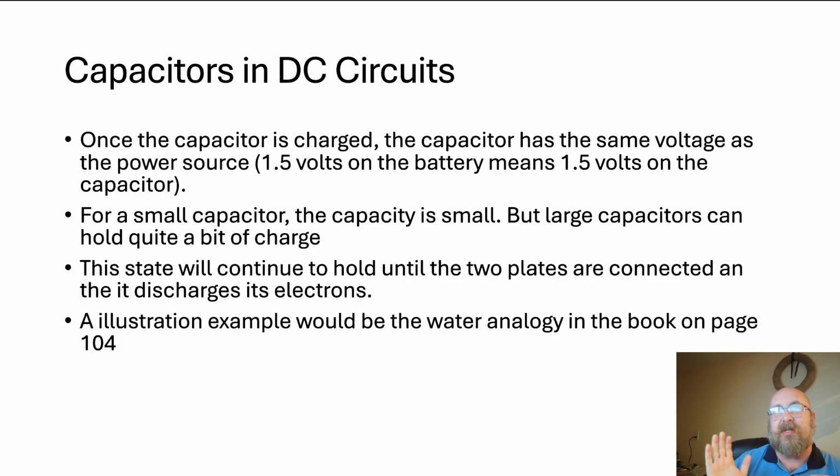This state will continue until the two plates are connected to one another. So they will stay charged, and they'll stay charged for a long time. In fact, one of the things that you have to be aware of when you're dealing with capacitors is that they are kind of dangerous. Your defibrillator has a little round portion of it off to one side. That's not the battery, that's a capacitor. And when it says charging and then does a discharge, that's from a capacitor. It will stay charged for a very long time, and then it will discharge very quickly.